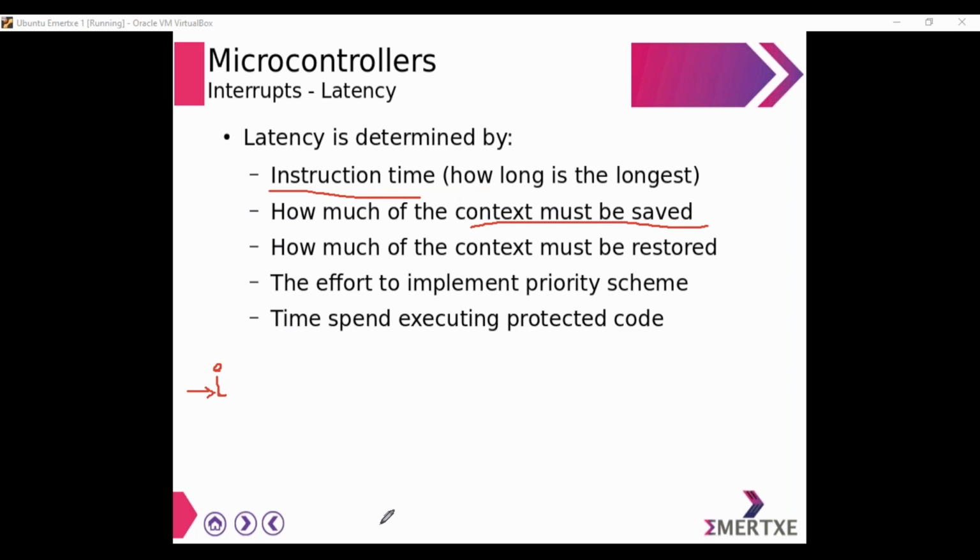I told you that when an interrupt occurs, there are chances that the ISR might make some changes to the contents of the registers. So I will generally back up the contents of the registers before the ISR is taken care of. It completely depends on how much data I have to back up.